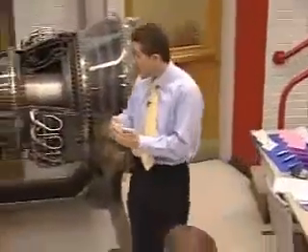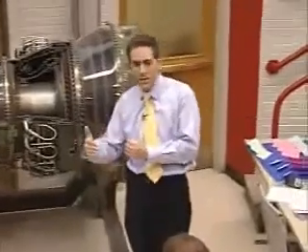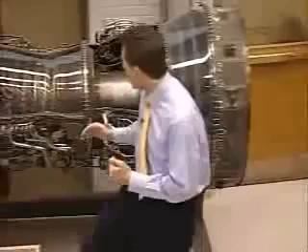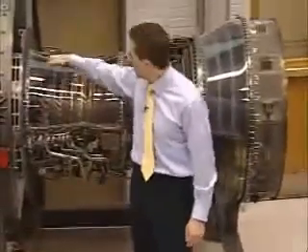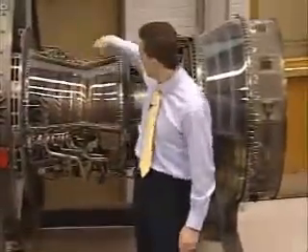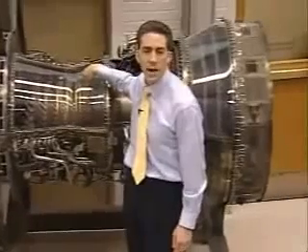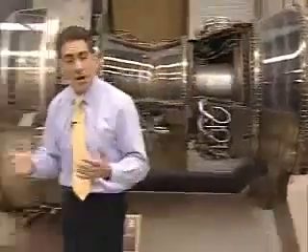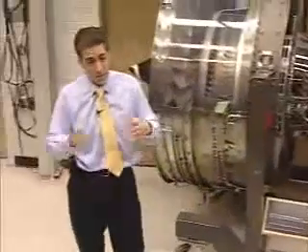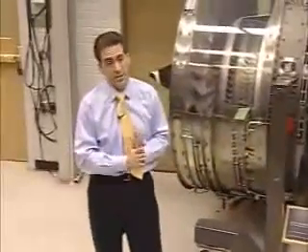Then what you typically do when you design, you say, I'm going to try and spin it a little faster or push that a little more. Or maybe I'll turn the flow a little bit more than I did in the past so I could eke out a little bit more pressure rise per blade row. And if I'm really good and I do that for all my blade rows, maybe I don't have to carry around one of these back stages anymore. Now I shorten the whole engine. It gets lighter, improves my range. So you do it all at once, but with some knowledge of what you've done in the past.